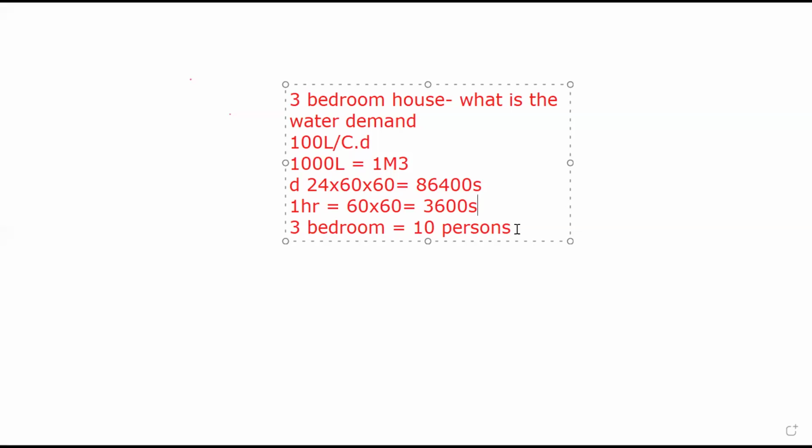So we're going to design water. If you design water based on hour or day, you're going to get the peak size. The one you design by day is the one bringing water to your reservoir. You don't design it by day because sometimes you pump 2 times in it. You pump every 12 hours. Sometimes you pump every 8 hours. So you do that design based on hourly demand. But in designing the water that comes to your house, you do based on seconds demand.